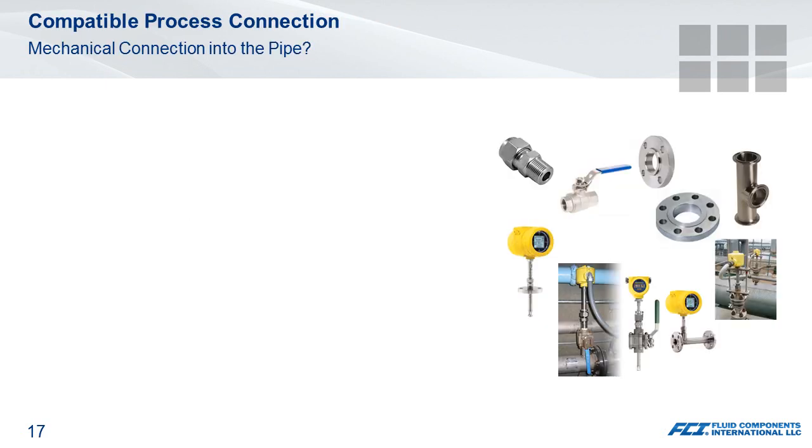So let's talk next about compatible process connections as being an essential requirement of specifying a thermal flow meter as well. Knowing the type of it, how it's going to be inserted into the pipe, what type of fitting, is it an NPT, a compression fitting, a flange? All those things need to be known up front.